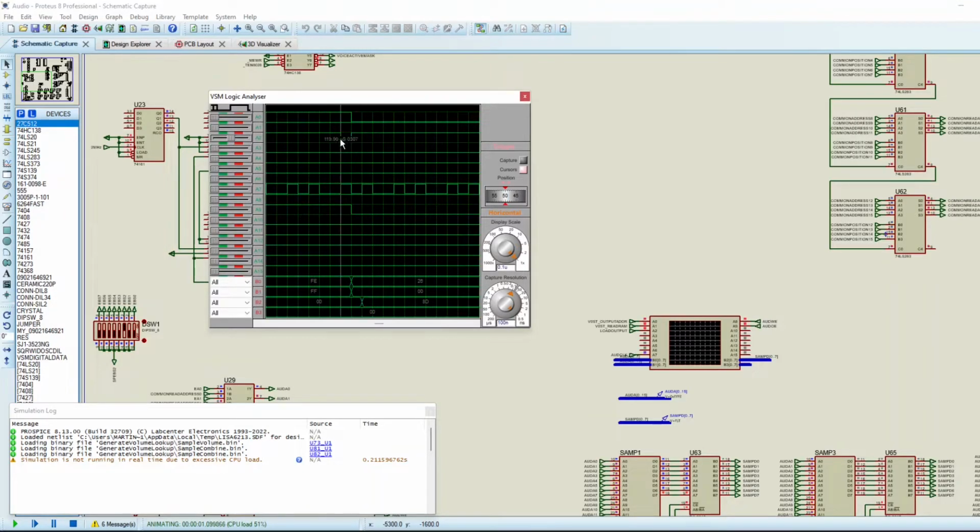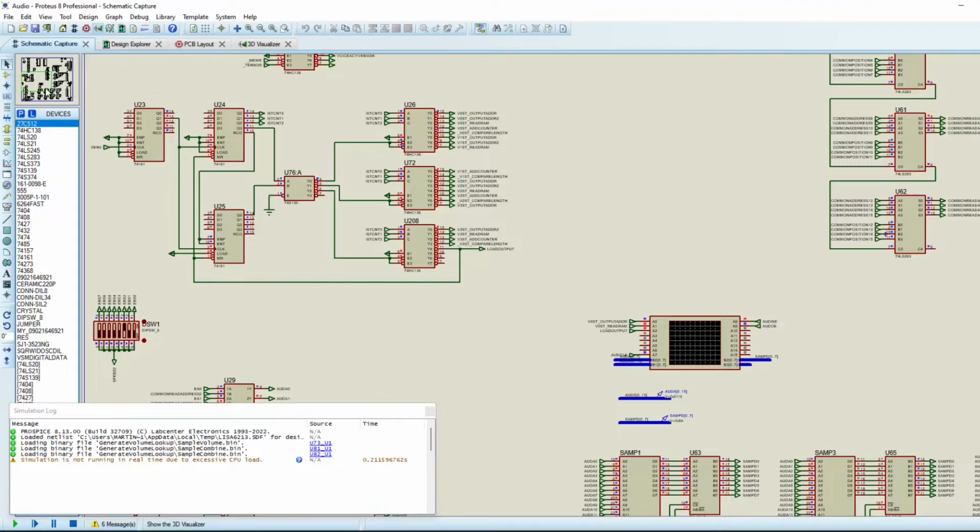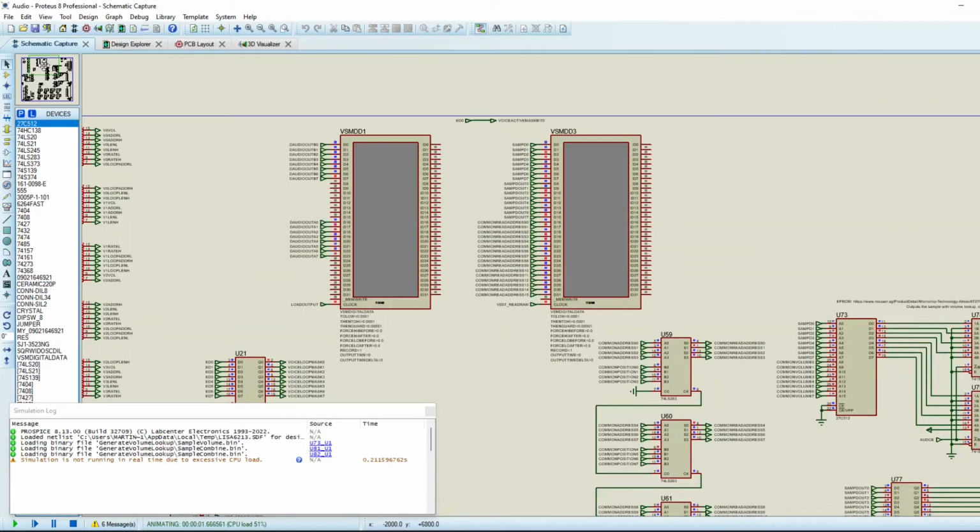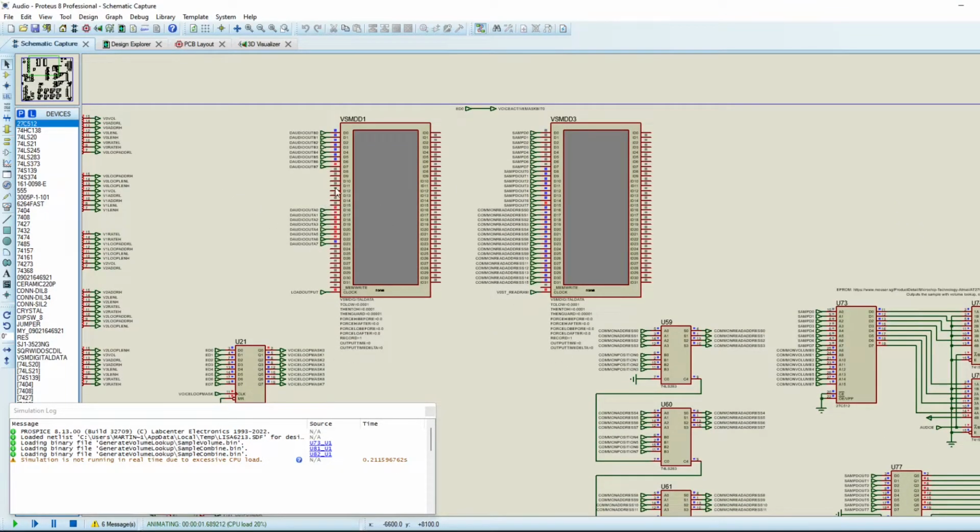You can see that this little reset state machine signal here actually has a noticeable time period, and that's because of the propagation delay in the state machine reset circuitry, so that's perfectly fine. You can see here that the address and the sample data being read come through, but because it's simulating very slowly, we can see the output data signal.